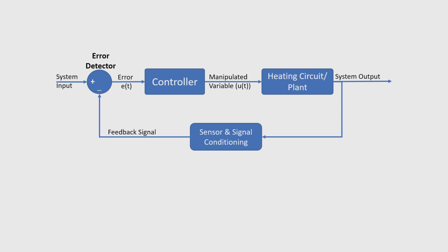In this case, as I have already told, we are generating a temperature on a transistor. The controller, which is nothing but LabVIEW plus a data acquisition device, cannot provide enough current to heat the transistor to the required temperature. As a result, we require a triggering circuit or driver circuit which takes the input from the controller and takes the power directly from the power supply and allows the plant to heat to a certain temperature.